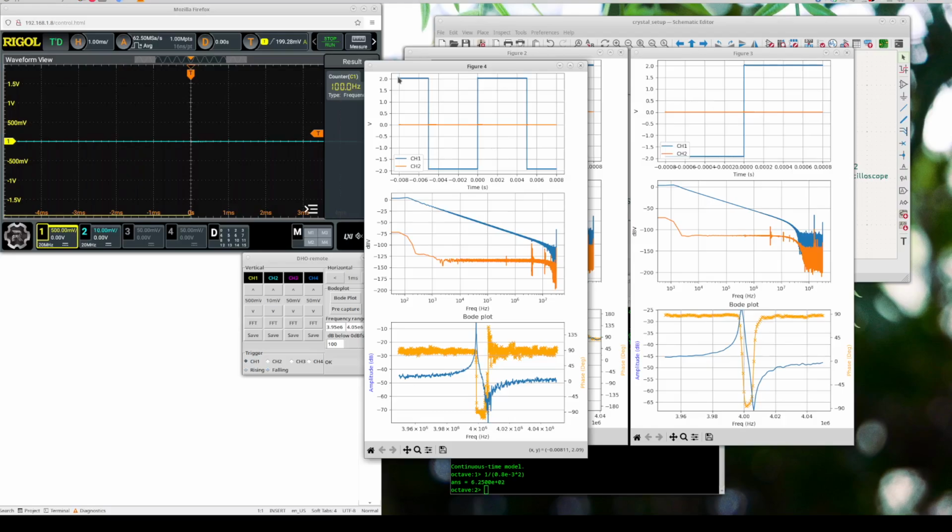So you get a discontinuity at the end of the entire sample that has been taken. The end sort of matches the beginning, so there's an artificial edge. To prevent that from spoiling the result, a window is taken, a Kaiser window. So only this part is sort of taken. But because that window is not perfect, you still see a little bit.